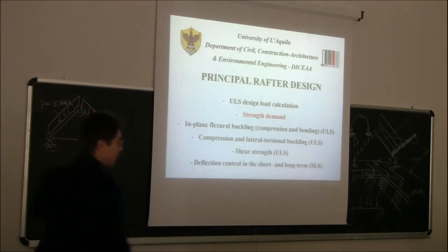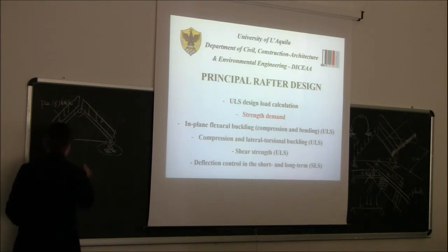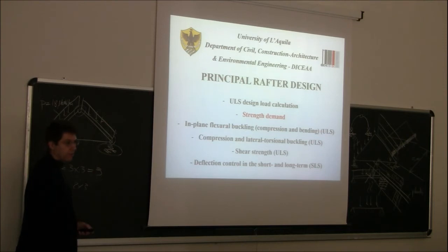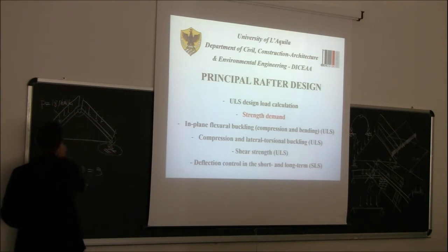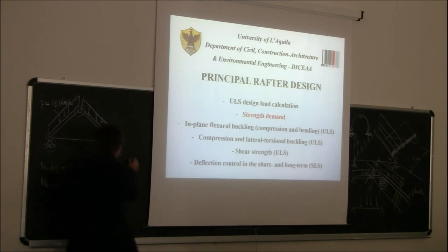So we said each internal pin takes away 2 degrees of freedom. So if you want, you do an equation: number of degrees of freedom equals 3 times 3, 9. Then number of degrees of restraint, we said 2 times 3 because we have 3 internal pins. And then we have 1 roller and 1 external hinge. So the external roller, how many degrees of freedom does it take away? This one. 1.